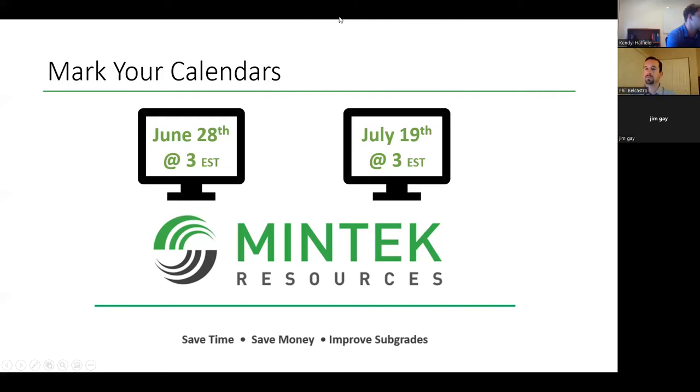You had a slide in your presentation to show the so-called net effect, right? Always be sure to check with your geotech, particularly in the field. If you're not seeing a reduction in your moisture content via the nuke gauge, be sure to ask the technician or somebody within that geotechnical firm, is that moisture content from the treated proctor or untreated proctor?